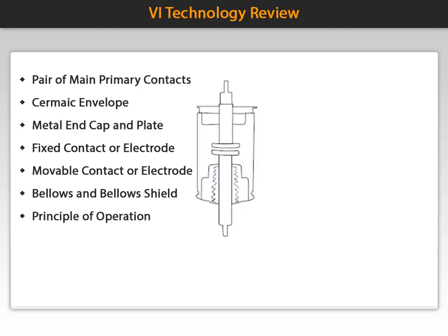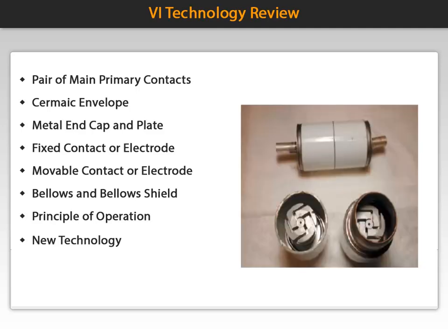When the contacts are separated, the arc is supported by ionized vapor derived from the contacts themselves rather than by ionized gas. Although the physics are complex, the interrupter works because the arc does not have a conducting path and cannot be sustained in a vacuum. New spiral-shaped contacts provide a self-induced magnetic effect that moves the arc around in a circular fashion, which minimizes the contact erosion.